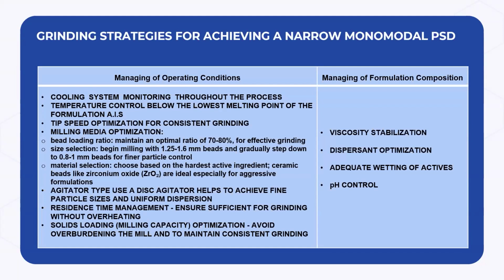Adjusting formulation composition. Rheology stabilizers. Add rheology stabilizers after grinding to maintain final viscosity. Dispersants, optimizing dispersant selection for even particle distribution. Wetting of actives, ensuring complete wetting to prevent clumping or reagglomeration. pH adjustment, monitoring and adjusting pH for ingredient stability and compatibility.